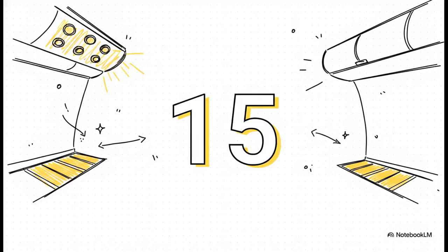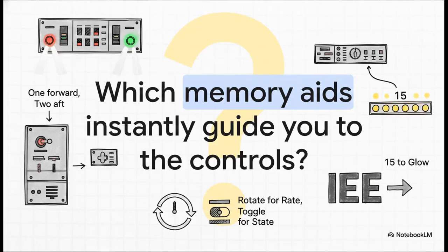Now, on the next-gen airplanes, there's one strict rule you have to follow for those photoluminescent floor path strips. The trick is 15 to glow. Prior to the first flight of the day, or really any time the aircraft has been in darkness for more than 3 hours, the cabin lights must remain on full bright for exactly 15 minutes. That 15-minute window ensures the strips absorb enough energy to glow and guide passengers to safety if the cabin ever goes pitch black.